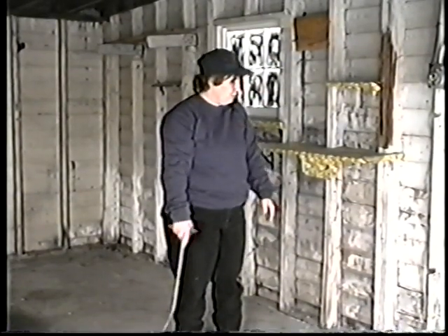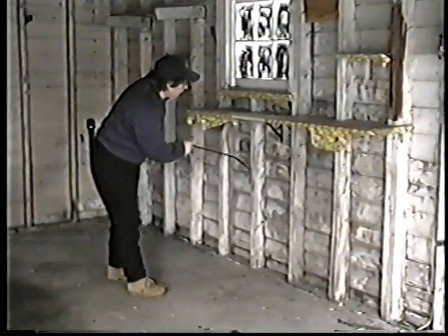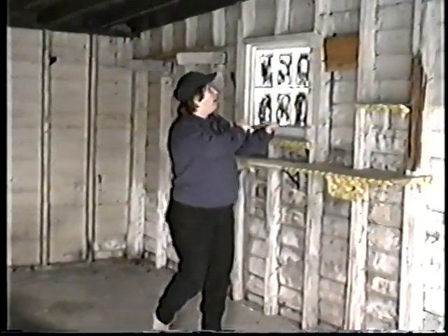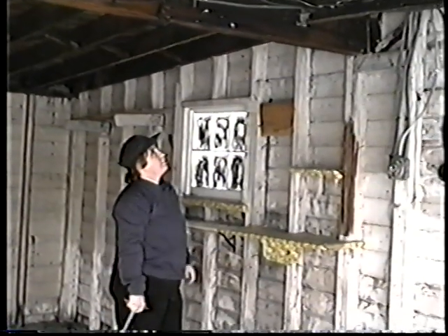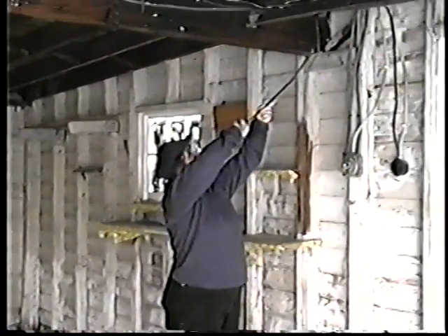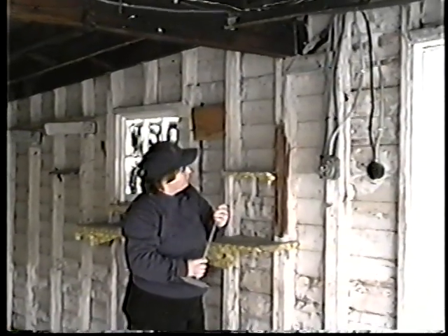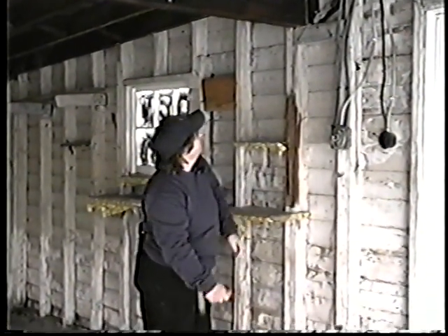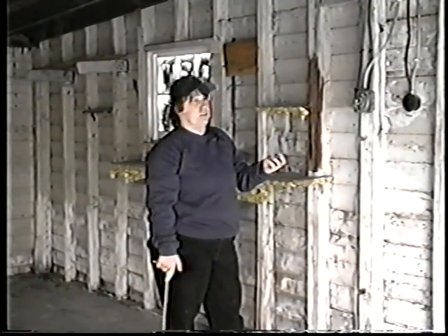In the inspection, the job is to poke. You want to get someone that's going to spend the time to poke around and look, both high and low, because there's water damage up here, but it doesn't seem to be termite infested. If you look up here, you'll see that there's some droppings and cobwebs. They actually look to be mouse droppings. Sometimes you'll find carpenter ant droppings, bodies from carpenter ants, or sawdust. That's what we call the frass of the carpenter ants.